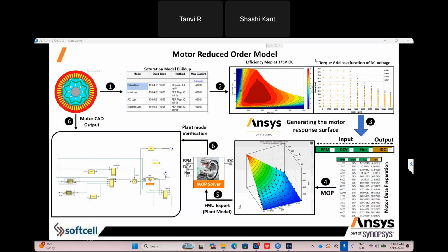Now the motor response is a must for this application. Sometimes we purchase motors from other vendors. Let's suppose you say, no, I want to create it as per my requirement. This software can help you also. We have Motor-CAD, where you have a template. You can just drag and drop, create the primary coil and secondary coil, create multiple components very easily, and simulate when this motor runs at a specific speed.